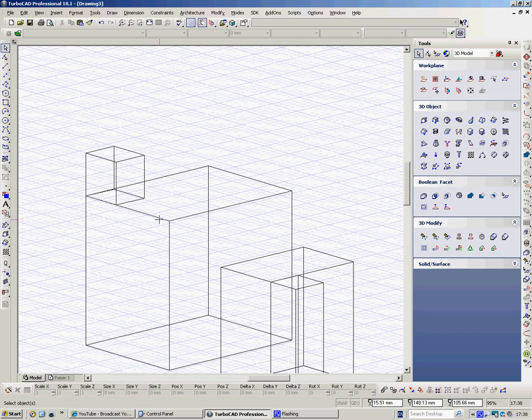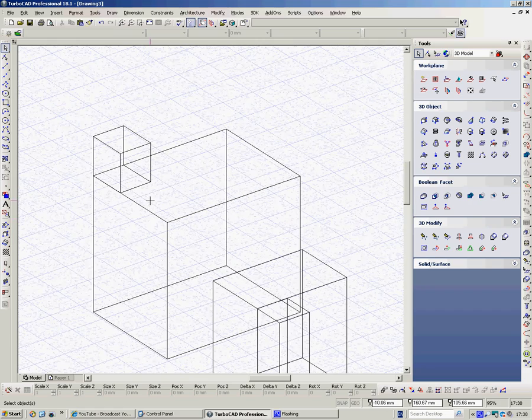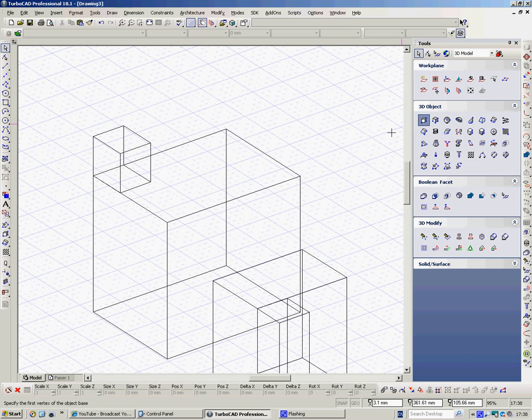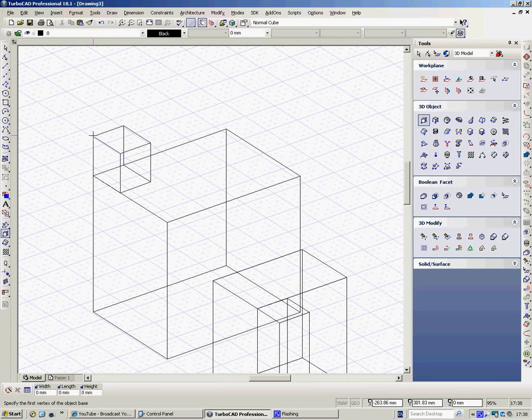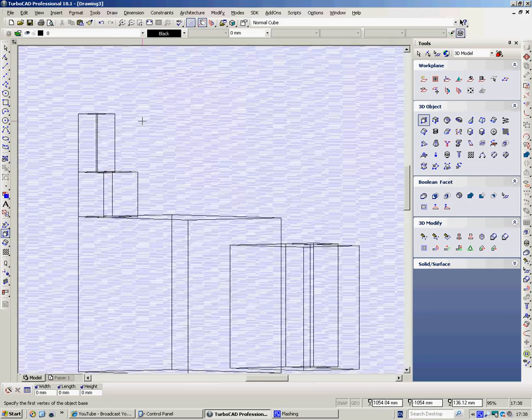So if you're drawing something quite complicated, chances are you'll draw that component, that part of the assembly, on its own, and then place it maybe using snaps. I mean, there's other ways, but this one's just about snaps. If it's just a straightforward box like that, you don't need to use the snaps. You can snap directly there, so I can go V and draw it, and it's there.